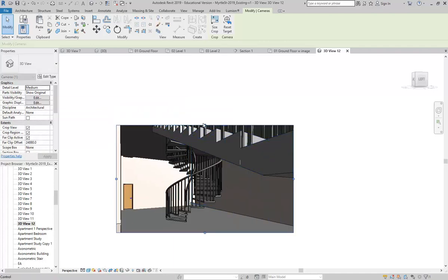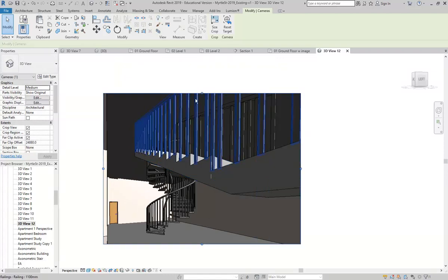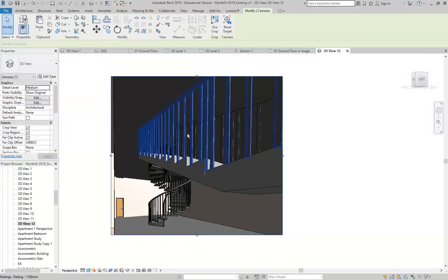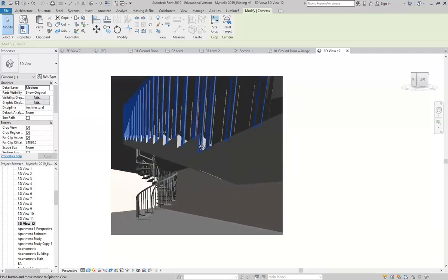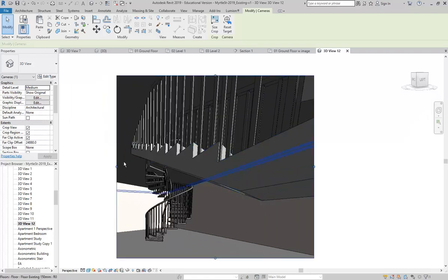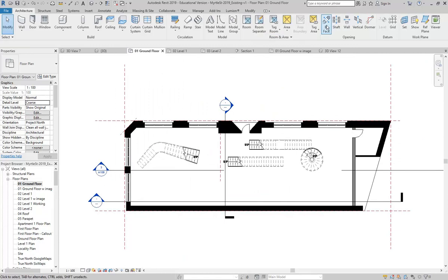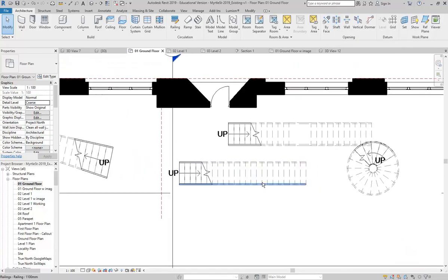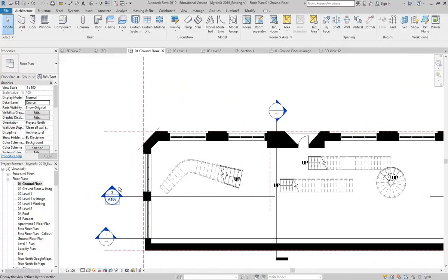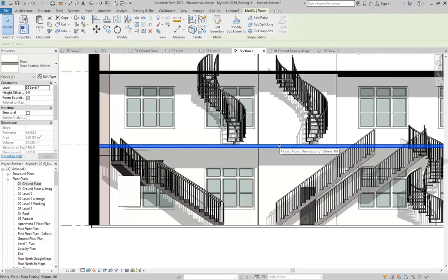Because when you're designing buildings or spaces, you want to be able to control that opening. It's actually a really important part of the design, usually. So you don't want it just to be an automatic thing. There are automatic tools in Revit that will give you cutouts. Okay, so later you'll see there's a shaft tool that does make holes for you. But in most cases, the easiest option is just to cut a hole in your floor yourself.